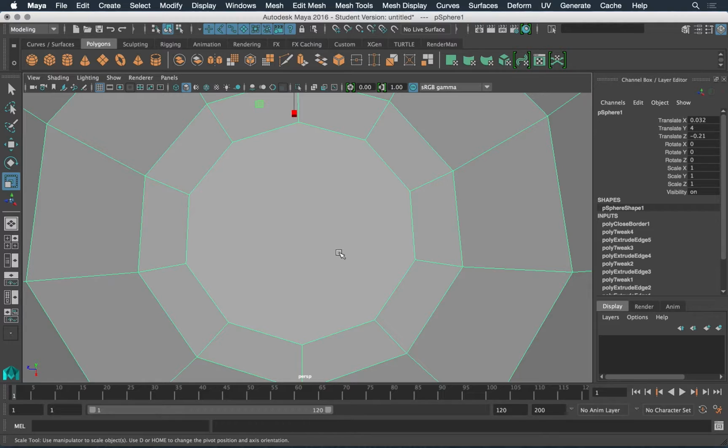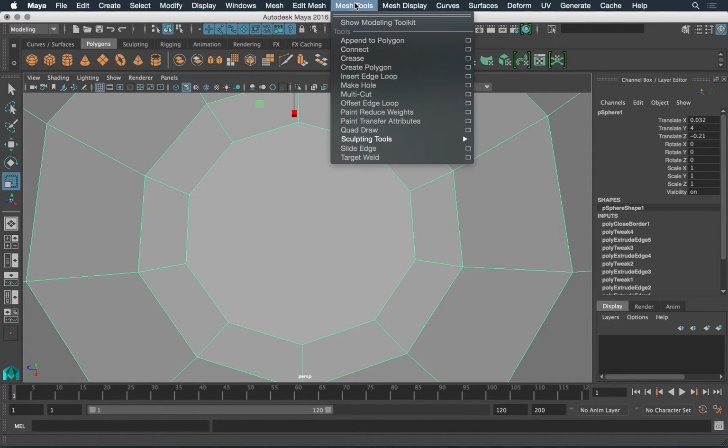So the tool to use to do that, and again I'm looking right into the bowl, is going to be actually one of the uncategorized ones, which is mesh tool and insert edge loop tool. Oh, sorry, not that one. Edge loop tool is inserting an edge around a ring, like a new loop. We actually want to draw our own, so we're actually going to go down 2 more from that and use multi-cut.